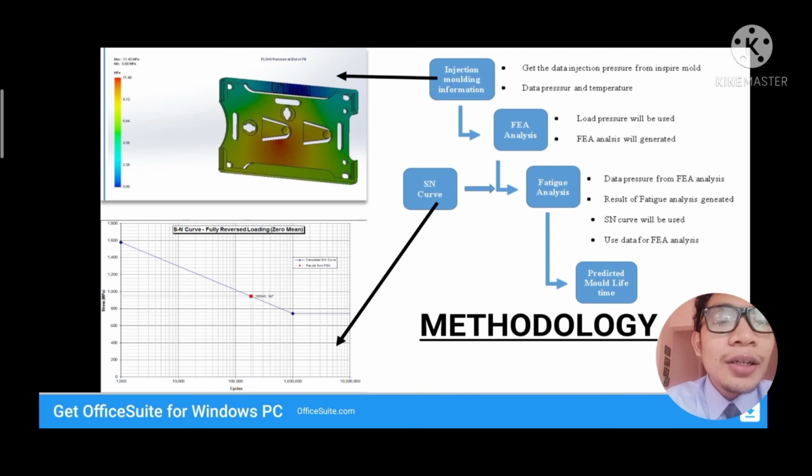For the methodology, first, I will get the injection molding information from Moldflow, and then do the FEA analysis, and lastly generate the fatigue analysis. We will obtain the S-N curve, and after that I will make the prediction of mold lifetime.